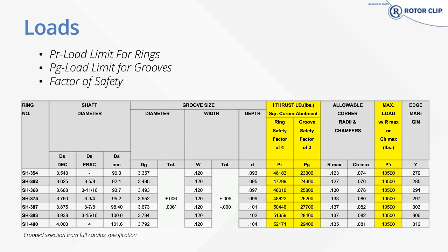Finally, we have the max load with a maximum radius or maximum chamfer. There's a decreased load in this scenario due to the moment from contact of the retained part. We'll touch on this a little bit more in a few slides.